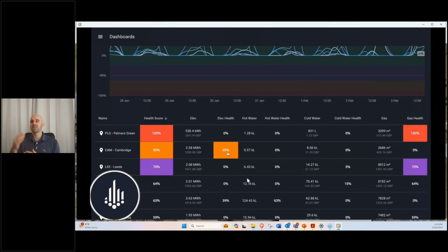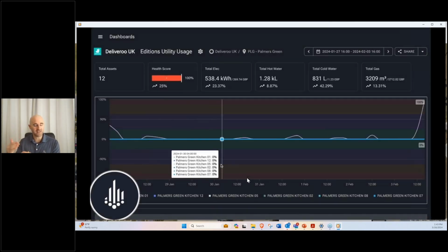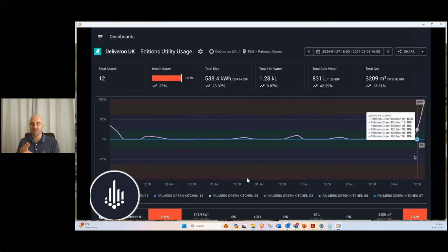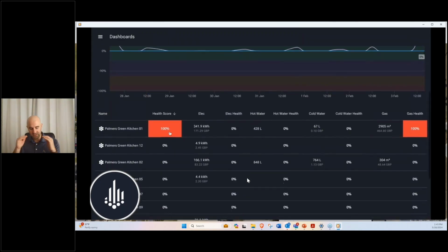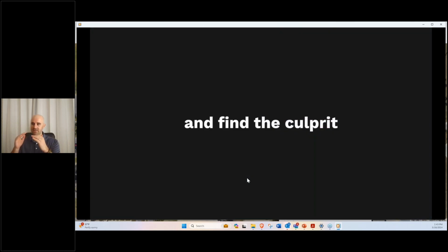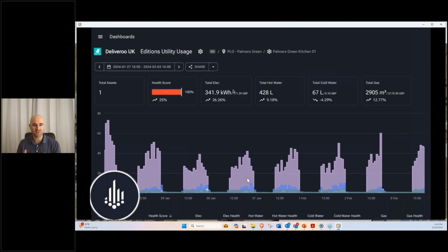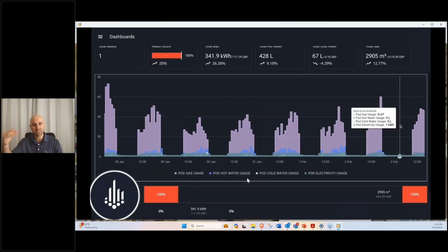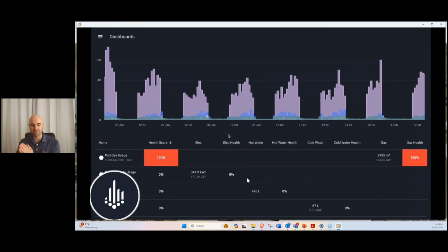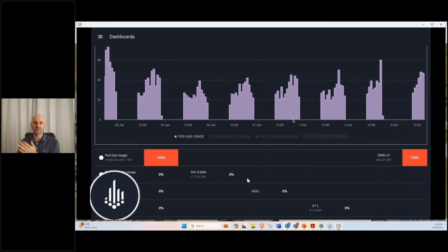Or to apply this to rotating equipment, which motor or pump is vibrating the hardest or seeing the most deviation from its threshold for healthy. So we can now tell maintenance, I got a report based on 100 or 1,000 different motors. The ones with the worst health score are pulled to the top, and they allow you to identify where to focus the maintenance efforts. So in utility consumption, it's going to be look for anomalies.